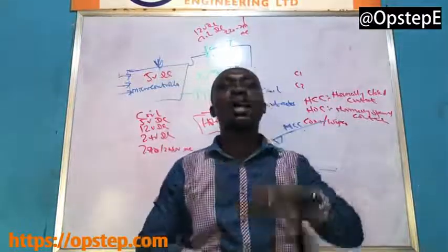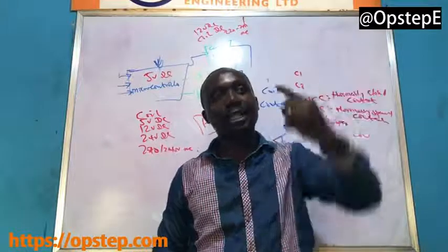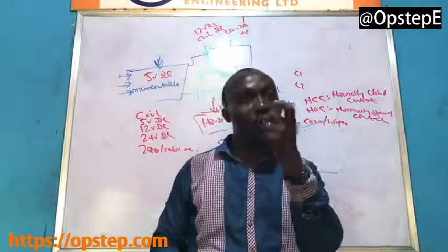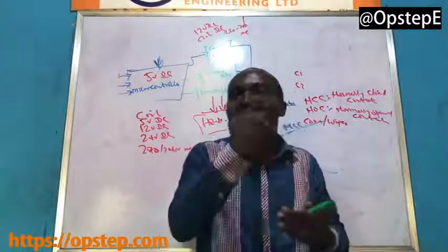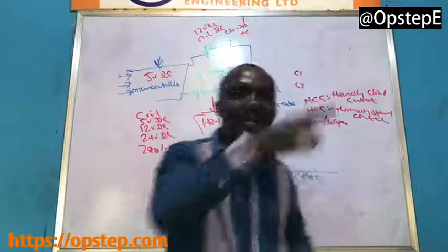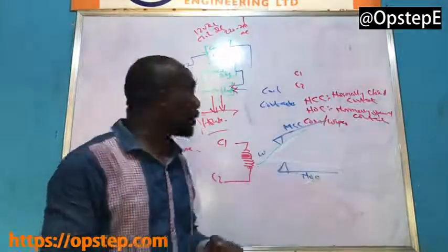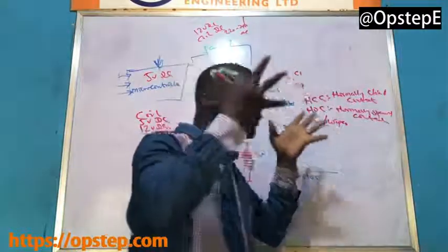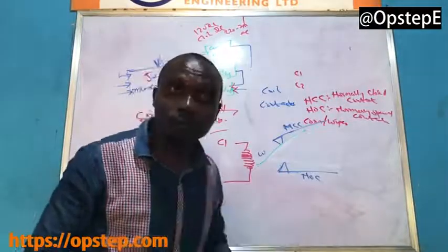Do you get it? Now, imagine you put a straw in the bottle. The rate at which you sip it will be based on the what? On the width of the straw. Are you following me? What the straw can carry or can allow is what will be delivered to you per time. That is the same with the contact of the relay. If the contact cannot stand the current you want to receive, when that load requests that current, the contact fries off.